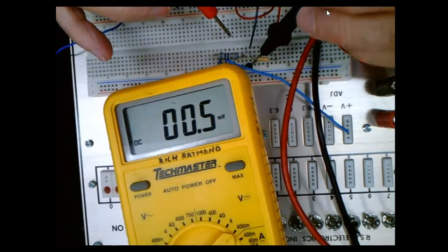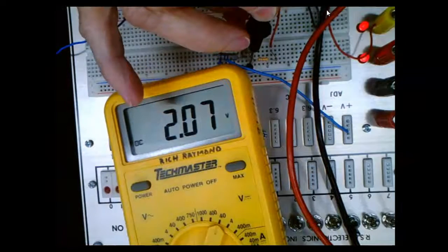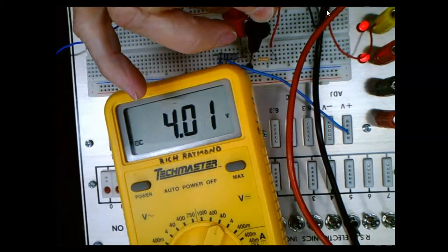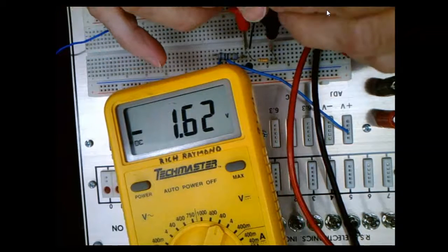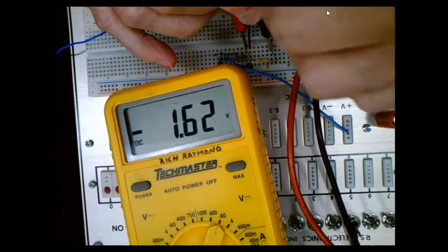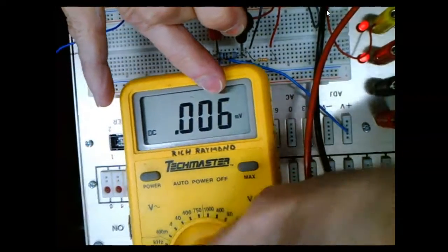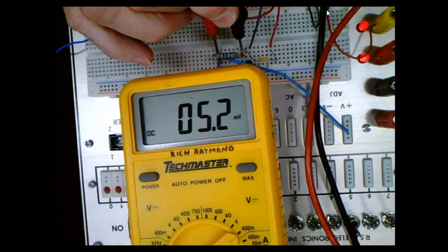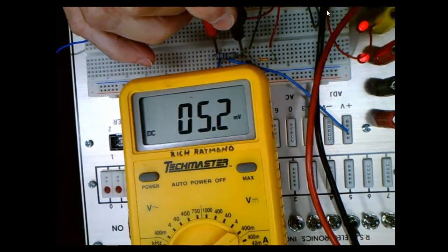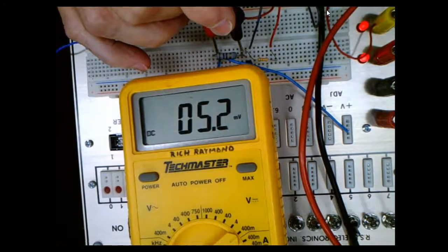Okay, so I'm going to go back to my voltage collector to emitter, and I'm going to set it to what's next? 4 volts. I'm going to come back and double check my base because we have to make sure this stays the same. It's good. Okay. So this base current had changed. I'm going to look at my 100 ohm resistor and it's dropping 5 millivolts. So notice the current stayed what? The same, right? Everybody okay? Ready to move on? We got 500 microamps both times so far.